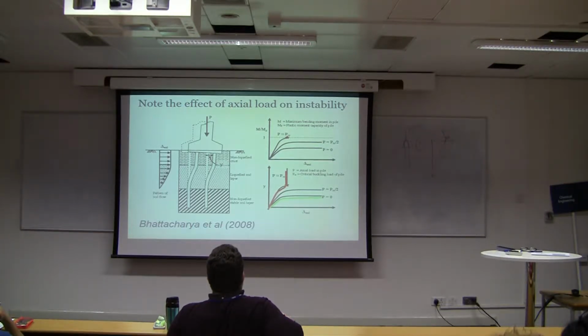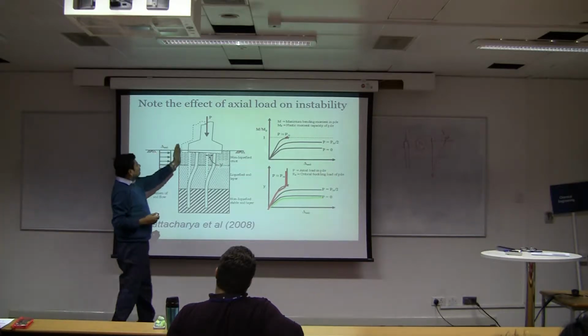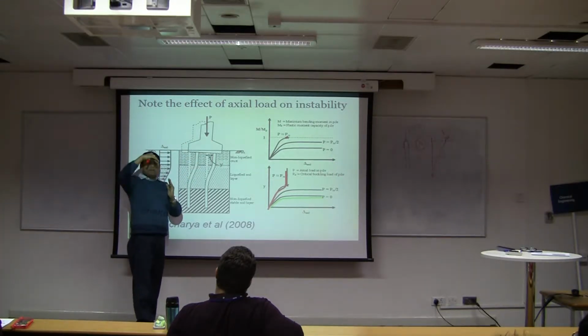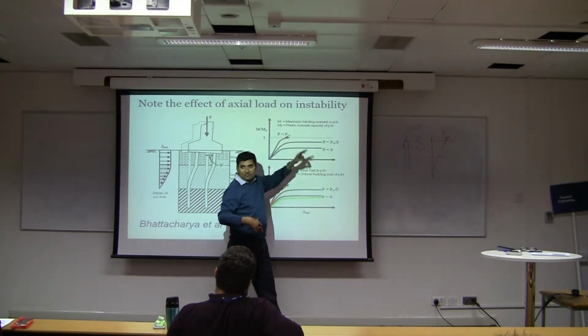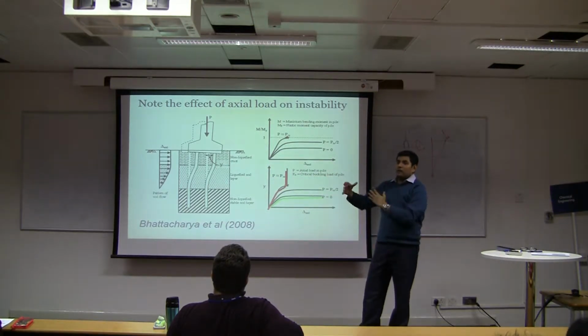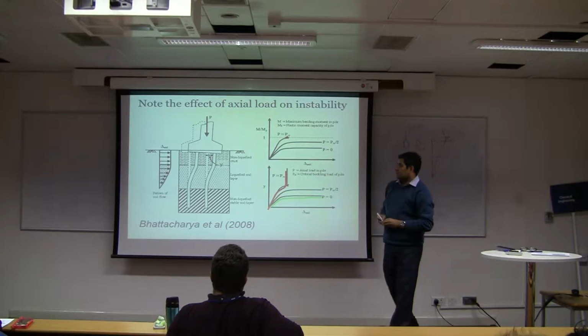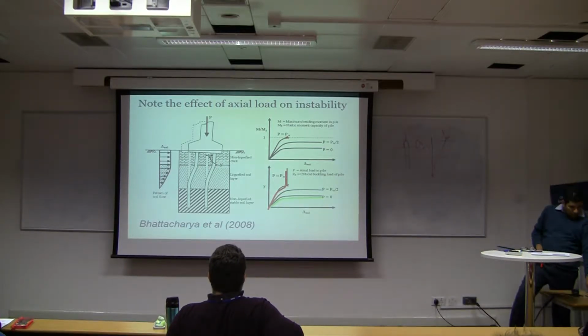Any question this side? And then what happens as this moves, the overturning moment increases, you get a bending moment exceeding the capacity, you get plastic hinge formation. Right? And you get the plastic hinge will form, pile will fail. Okay?